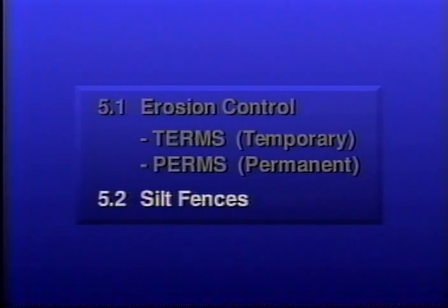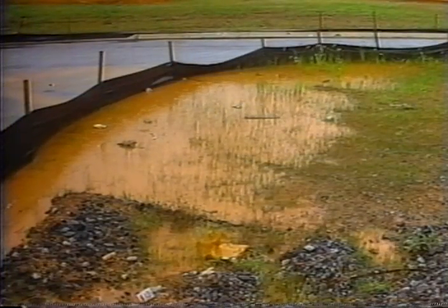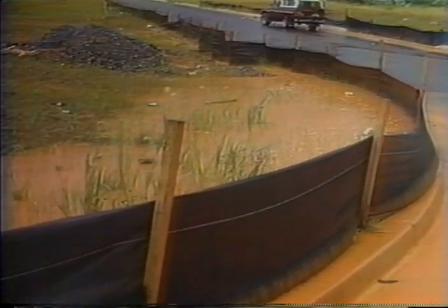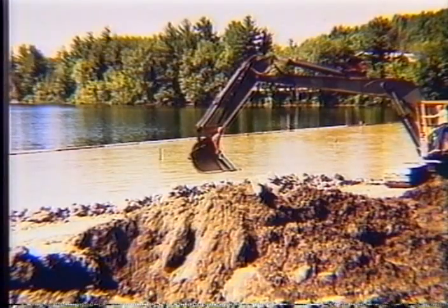Soil loss during construction can be temporarily arrested by using geosynthetic materials. Geotextile silt fences placed downslope from a construction site can trap sediment suspended in the runoff while allowing the clear water to pass through. In a similar application in water, a geotextile turbidity curtain will reduce water velocity, trapping the sediment and allowing the clean water through. This prevents water disturbance and contamination outside the construction area.